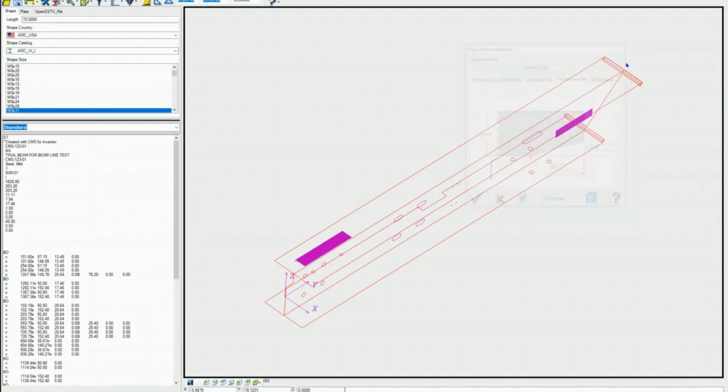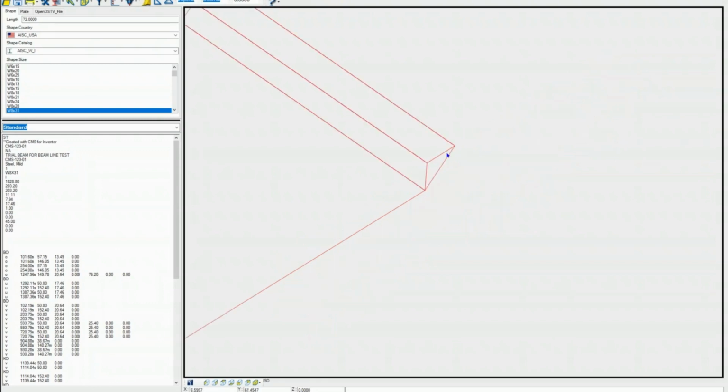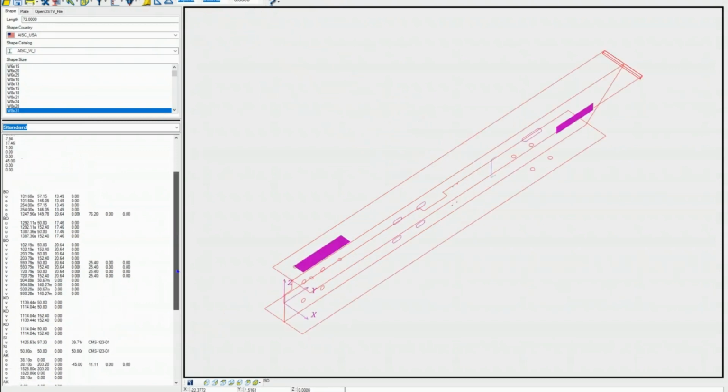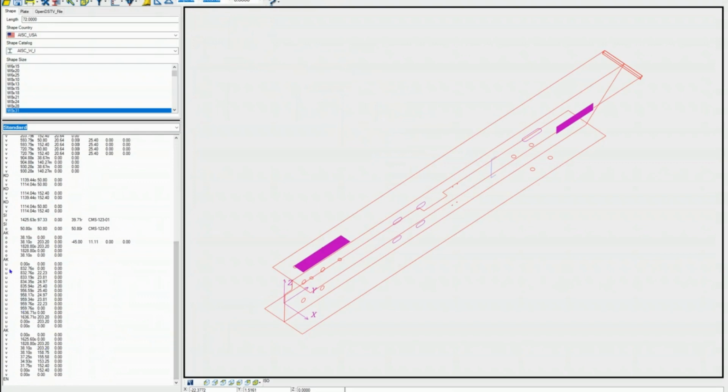Okay. And then if I don't want this bevel, for example, right, I can hover over with my mouse and delete the operation that I don't want, right? And then the NC1 file will be updated as well. As you see on this EU, there are no bevel descriptions like those ones.